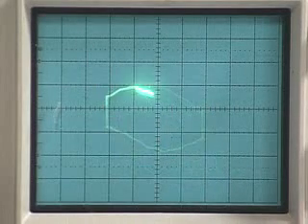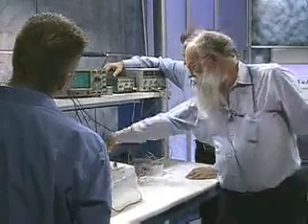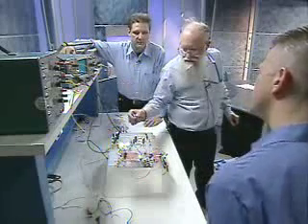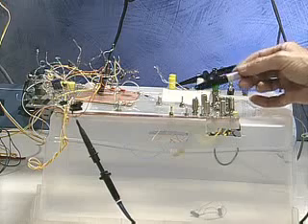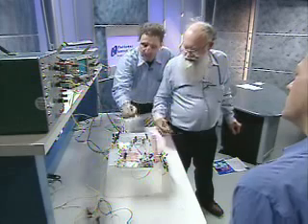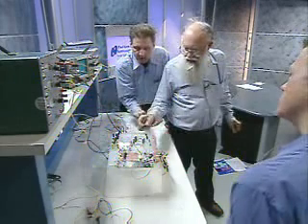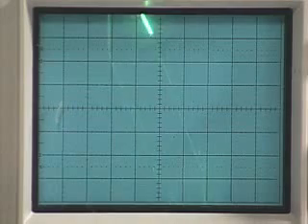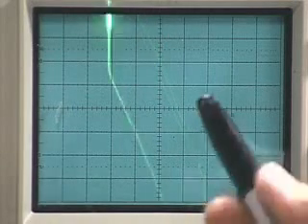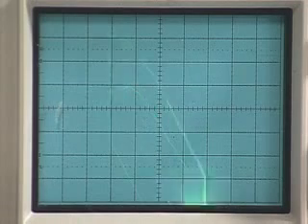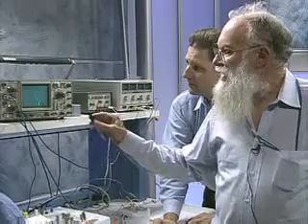So here we have the current coming in on 2 wires into this signal, where we have a separate power supply at plus minus 12 volts to distinguish the difference between this voltage and this voltage. This chunk of wire is what you're measuring. A tiny little chunk of copper wire, 1 milliohm actually, measuring that at the part per million level. Watch it cool off. As it cools off, it's got very small error. As the bridge is balanced, it will go straight.